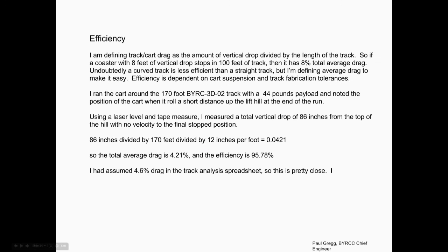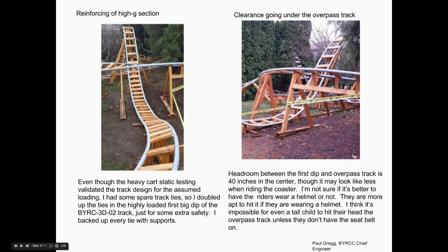I won't go through the rest of this. I've covered most of it in other videos, but the only other thing I'd say is these 2x4 frames. I put a counterbore 3.5-inch number 10 screw in the bottom, 2 of those down there, 2 here, maybe 1 up through the bottom and 1 through the side. There's a counterbore number 10 screw holding these 2 together, and then there's 3 on top through the tie, 1 into the inside board and 2 into the other one. So that's a pretty simple frame, and it's worked out really well. That's how I build my frames.